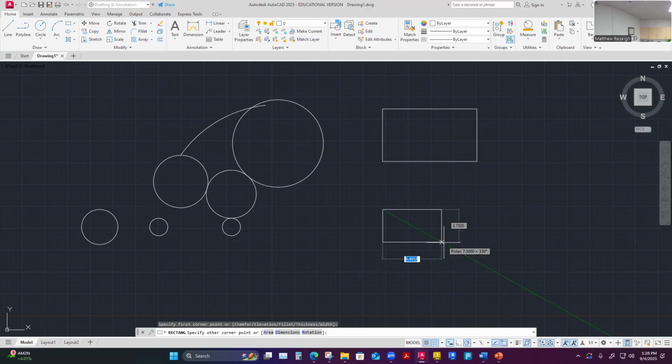I just enter that. I'm just going to do 6, but don't push enter. Maybe I'll say it's 6 wide. I entered 6 there. To get to the other box, which says 375 right now, you just hit tab. This is going to be a common command we use a lot when you have multiple inputs on geometry. In order to get around to them, it's just tab. And then I'm over to the other input point. You can see that it established a little lock on that rectangular width. I put in 6, it's locked.